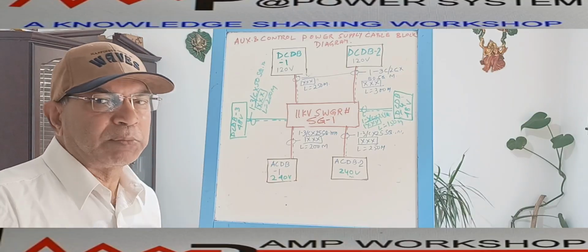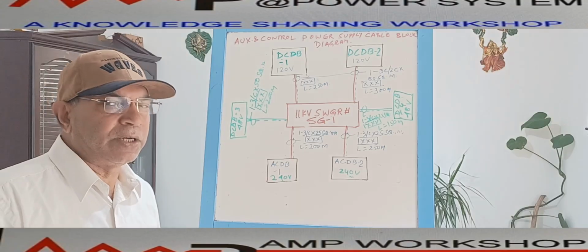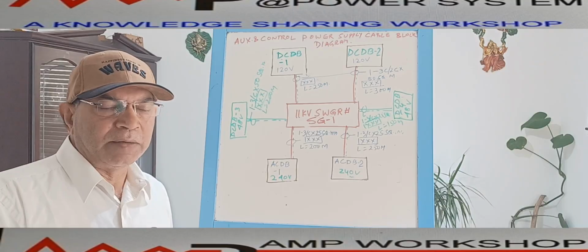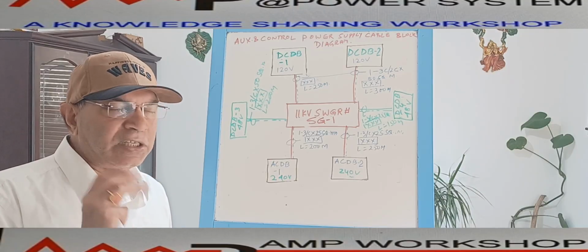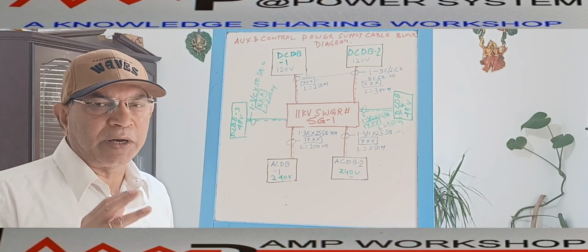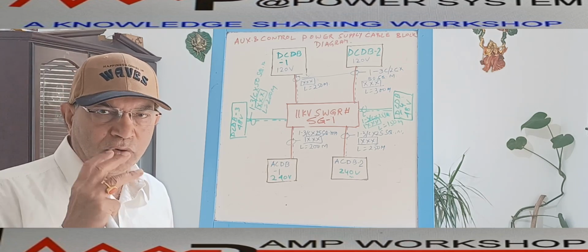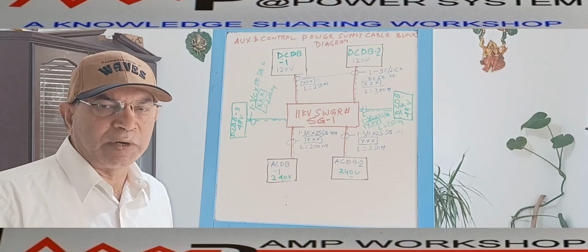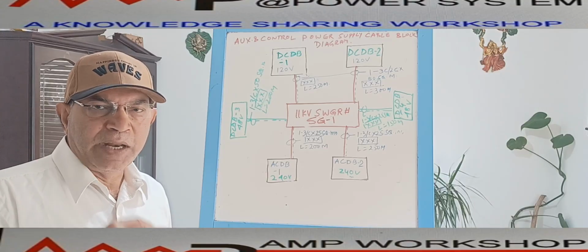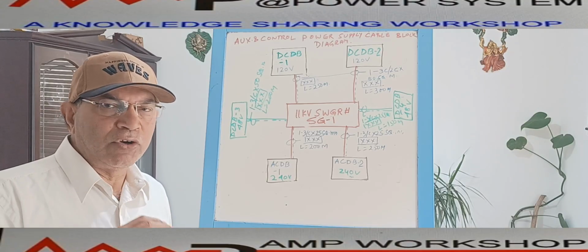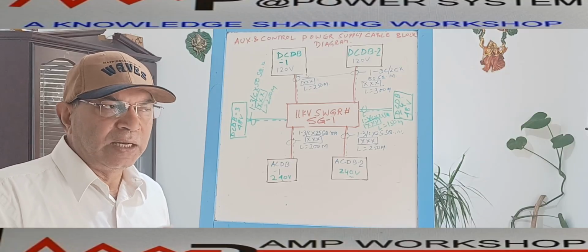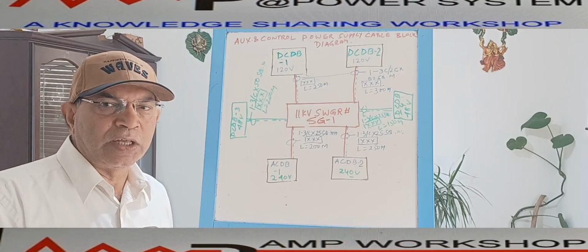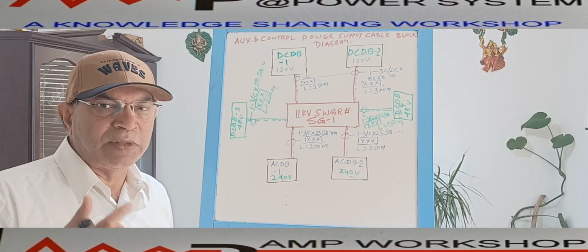So to supply this power, we use some special logic over here. We generally do not give one supply to the panel, because this is very critical. If the DC power is off, immediately the circuit breaker will not be able to operate. Suppose the 120 volt DC power, which is used for the electrical control, that is circuit breaker operation, closing, opening, and various auxiliary relays, suddenly fails, then the entire operation will be stopped. And moreover, if the breaker is already closed, then it may fail to trip. That will be very dangerous.